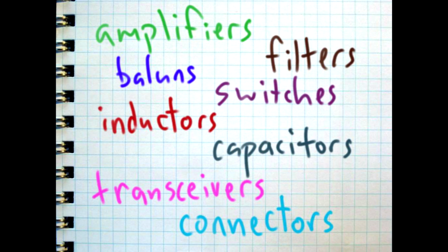So, things that you want to look for in these components, some of them I mentioned already, but like ease of use is number 1 for me personally. 50 ohm interfaces, look for that. In filters, look for the frequency response. Look in the data sheet and look for the graph that shows you how much it passes the frequency of interest and how much it blocks other frequencies.